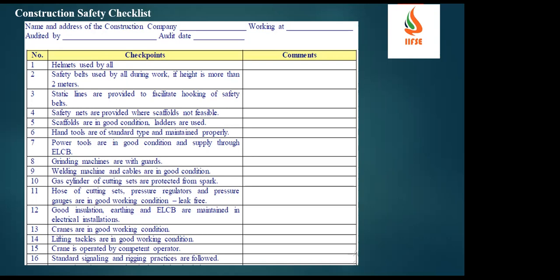to avoid the fall or collapse of the scaffold. We should barricade in and around the scaffold so that vehicle movement is restricted. Otherwise, the truck drivers may hit the scaffold and the complete scaffold may collapse. Also, for internal transfer, people should not cross over from one scaffold to another. We should have a proper platform for changing, and give proper protection to avoid the fall of people. Okay, those are the checkpoints we have to check.